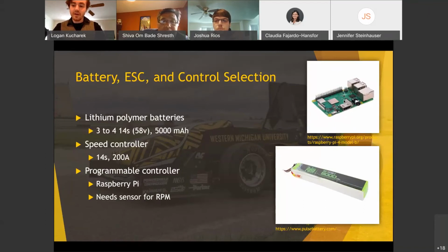They can be wired in parallel to provide more capacity, and it is only recommended to purchase 3 or 4 of these batteries for initial testing, as total turbo runtime has not been established, nor will be without bench and track testing, especially in the endurance event of 30 minutes. At lower than peak draw of 50 amps sustained for 30 minutes, 25 amp hours of battery capacity will be necessary. And that's about 20 pounds of battery, which is a lot.